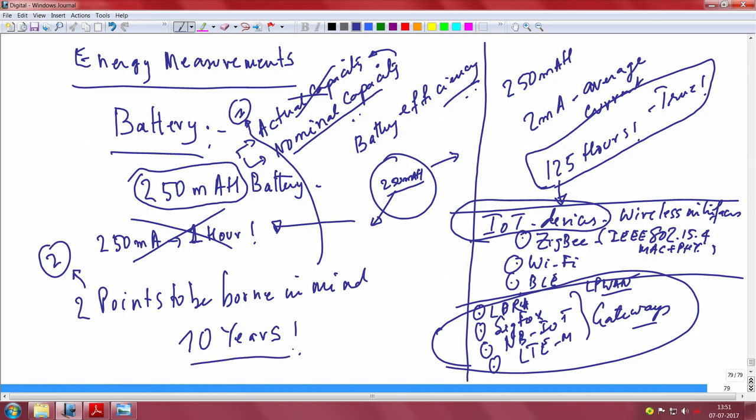If you do not design your systems for 10 years, I do not think it is worth even trying for in an IoT application. However, gateway, obviously you may have to be very careful. It will also have to live long as well, and it should not be a power guzzling part.